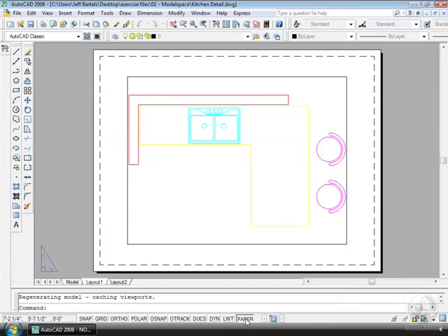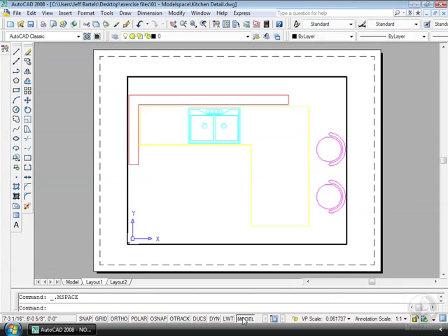Let me click on model. Yeah, that could be scary if you're just using the program. Hey, my screen looks different. What this actually did was it popped us out onto a layout tab. And if you think you're going to return by clicking on this again, unfortunately, you don't. So be careful of that guy.